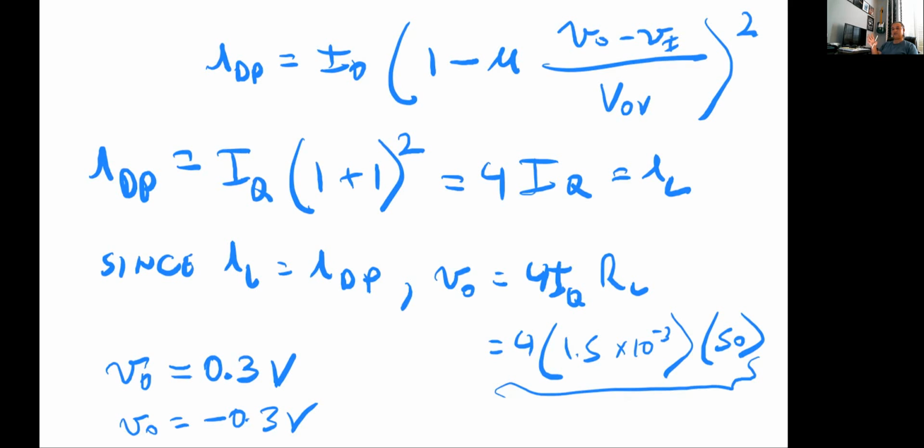The transistor supplying the load is deep in saturation. So the voltage from drain to source of each transistor when it's supplying that load is very small, and then it's going to make the voltage across the load the highest. So that gives you the highest linear range of the amplifier. Okay.